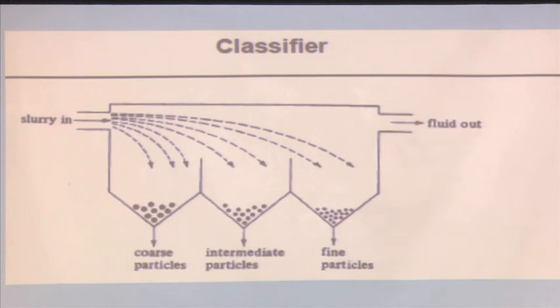So, this dimension, mainly the width of this, I can design if I have a basic understanding of basic flow problem, and the heart of this is the settling velocity problem. Okay. So, I can also design. It is not that simple that you just have these chambers and your particles will be collected in a separated form. That is where the design comes in.